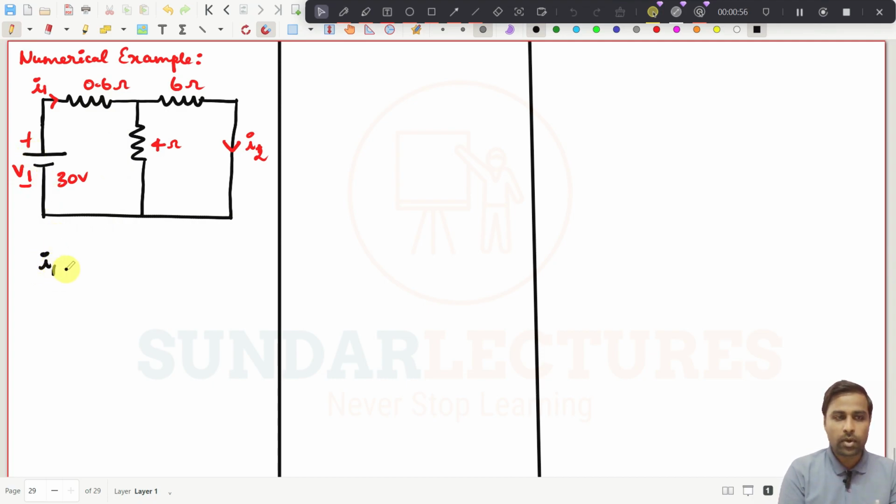So I1 can be written as, these two are connected in parallel and this is connected in series with this parallel combination. So it will be V1 divided by this resistance 0.6 plus, this is connected in parallel, right? So it will be 4 into 6 divided by 4 plus 6. So what is V1? V1 is 30.